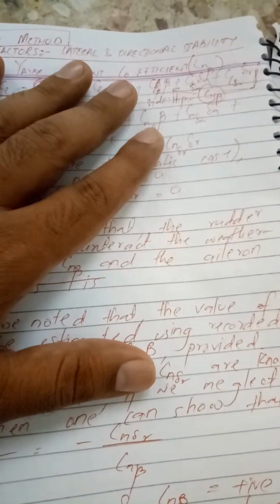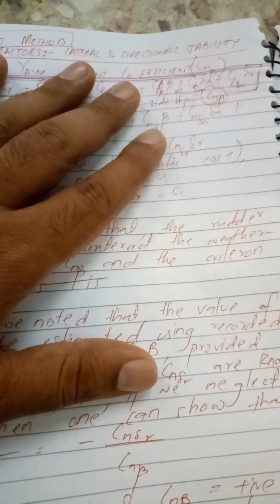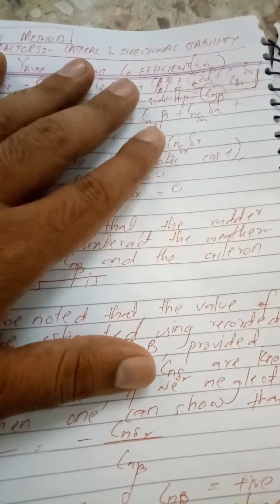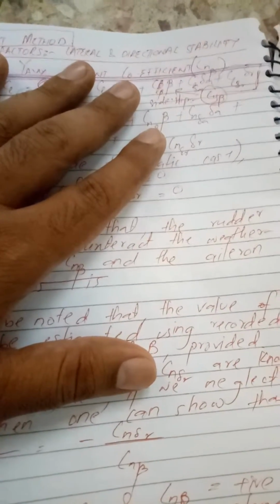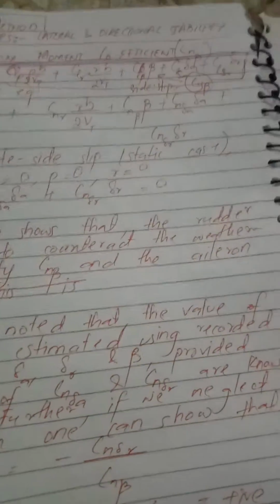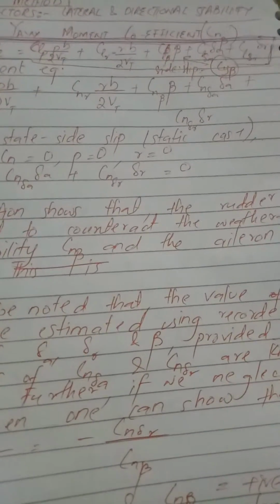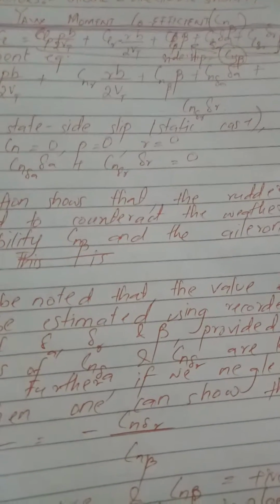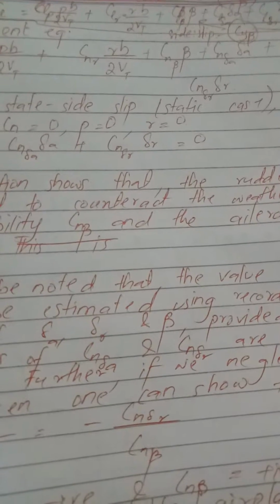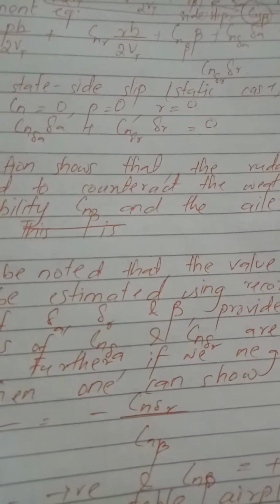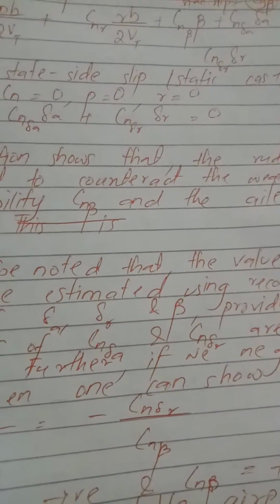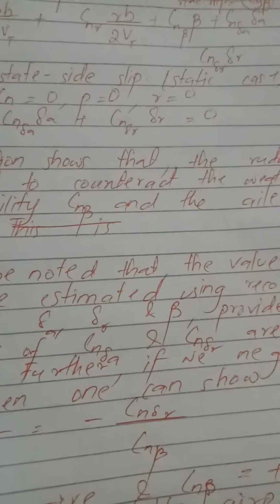As far as the directional stability is concerned, let's see in the next video how these factors or components will play out as far as the rolling moment coefficient is concerned, and obviously that would be under the paradigm of lateral stability, when we're talking about the steady side slip maneuver, where beta is equal to 0, and also the other assumptions that we have taken as far as the lambda r, velocity by the airspeed indicator, and altitude is also measured by the instrument.